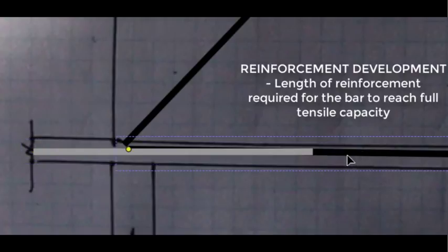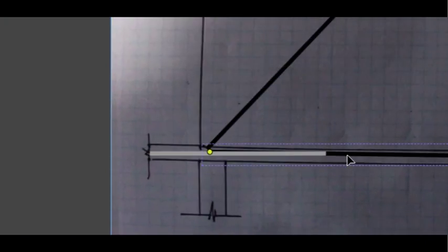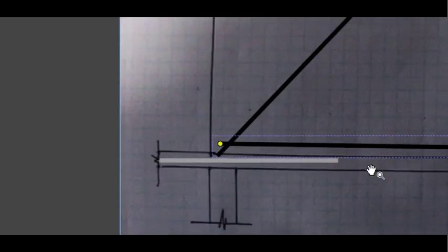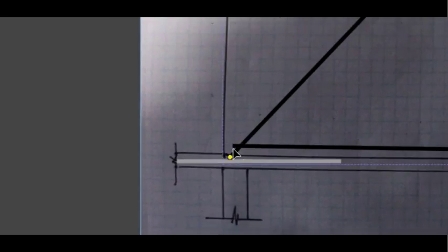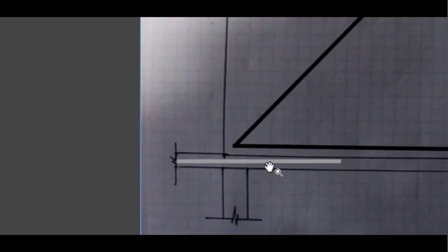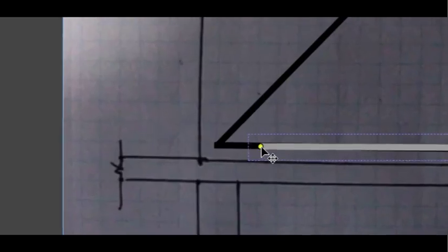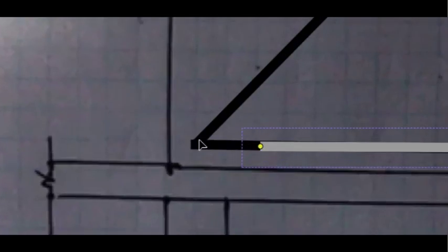But what would happen if, from the very start of the design process, we move the node inside the precast wall? In this scenario, it would move up like that. So now we would have to put our reinforcement inside the wall. For this, you can see straight away, it's hard to get the full development length required past the center of the node, as the edge of the wall is in the way.